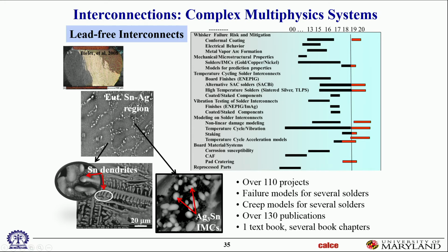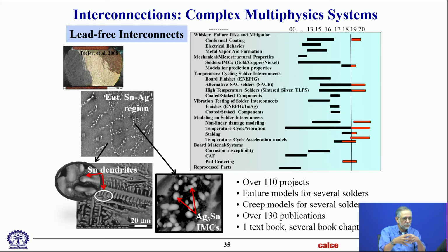With whiskers, under long-term mechanical stresses, you start to see little single crystal whiskers growing out of the surface. Visually it looks like a fuzz ball, a ball with some fuzzy hair on it. If you look under a microscope, each of those hairs is basically a single crystal extrusion of tin. In this case, tin. For other metals, it'll be whiskers of whatever that base metal is.